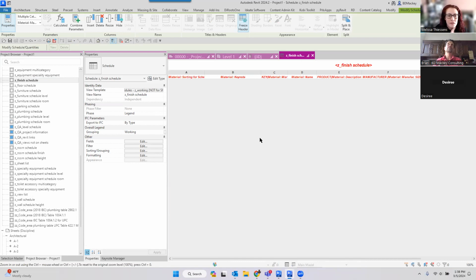Yeah, and where I've really used the paint parameter is I've done a lot of crazy precast things, and then the reveals of the precast, they want them to be black. I didn't want to do 5 different extrusions in this crazy precast thing. It's like, oh, there's 6 reveals. So I literally just painted the parameter on the bottom, the middle, and the top edge of that reveal, and went through and did it that way too.